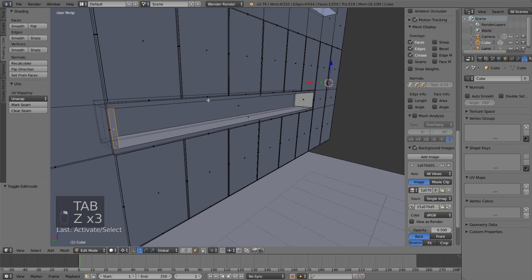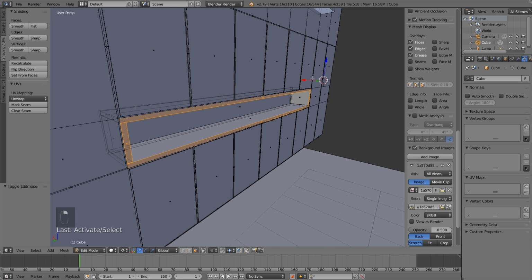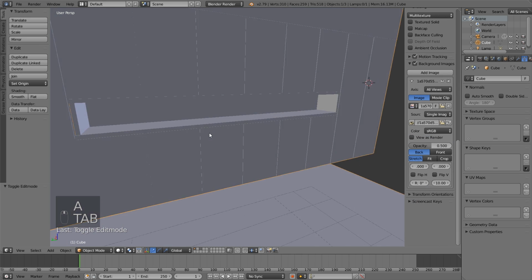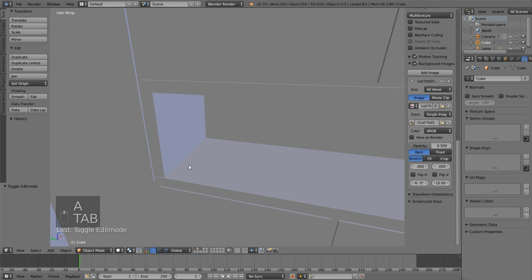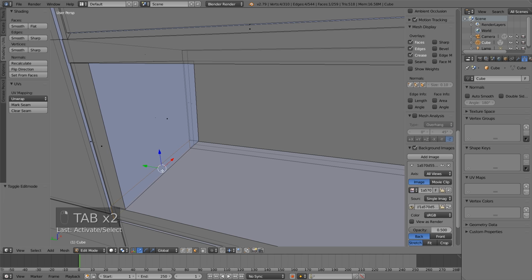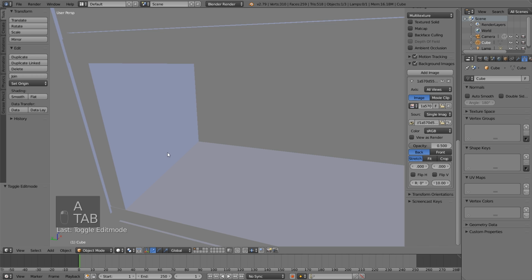Now maybe the wood should stick out a little bit now too, just to kind of match those sticking up. So you grab the edge faces. You're going to change this back to medium point. The edge faces there though, and pull those out a little bit too, just to kind of match. All right. It looks like this board needs to come down a little bit. So grab that bottom face and pull it down a tad.